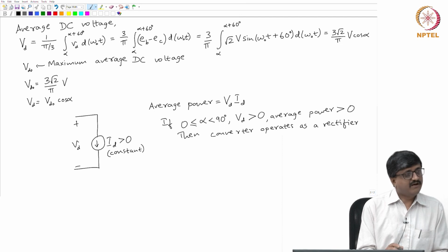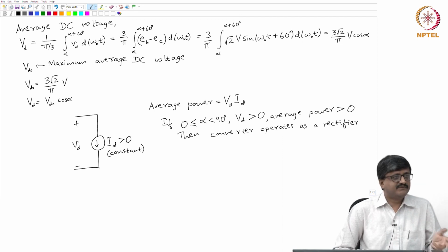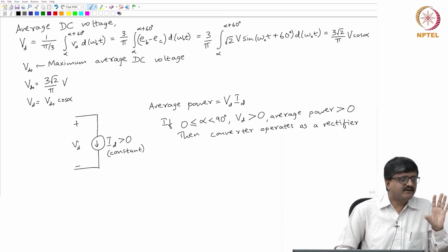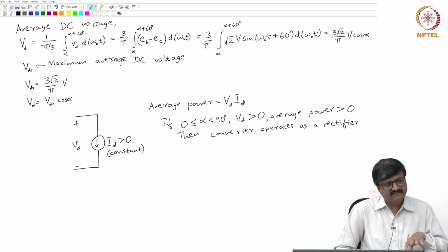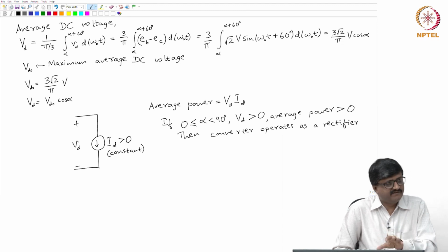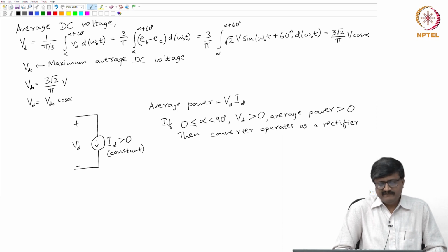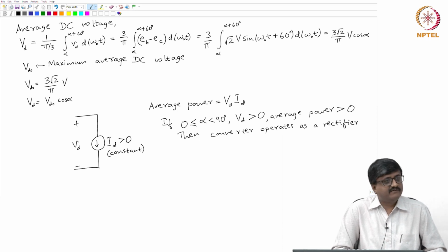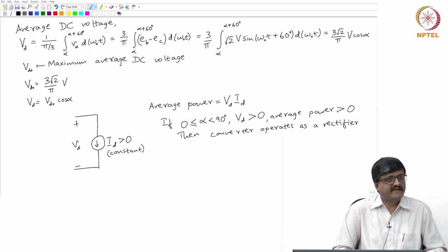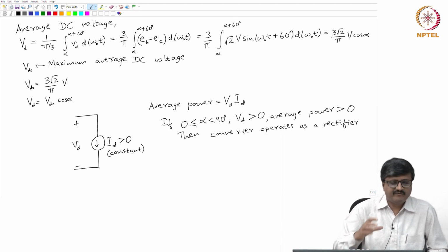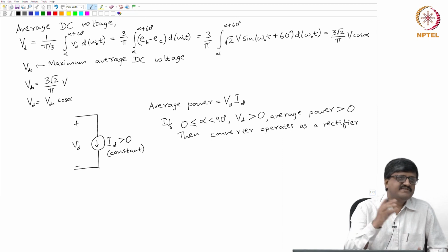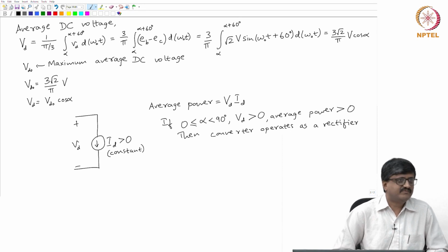Okay. Similarly, what about the current on the AC side? The currents are not sinusoidal. So, on the AC side voltages are as required, ideal, but currents are not sinusoidal. On the DC side current is ideal by our assumption, it is constant, but voltage is not ideal. So, when we say something is not equal to what is desired, then we want to find out by how much it is deviating from ideal. So, how do we do that?